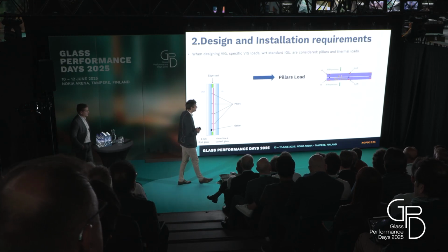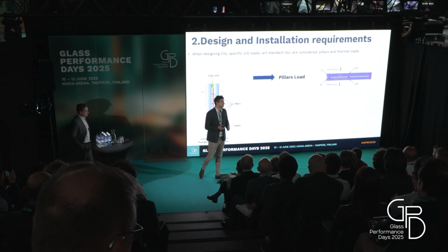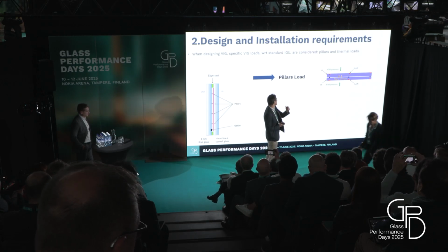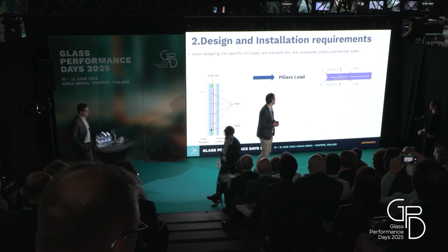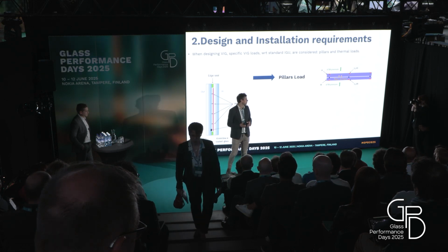So the pillar loads, it's actually the counter reaction to the atmospheric pressure, as I said before. And so due to this, the pillar will have a counter effect and create local stress on the edge of the glass, as you can see here on the sketch.